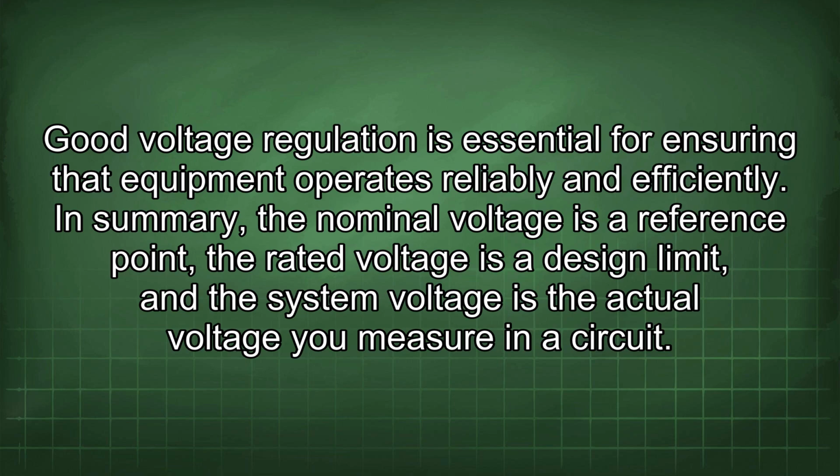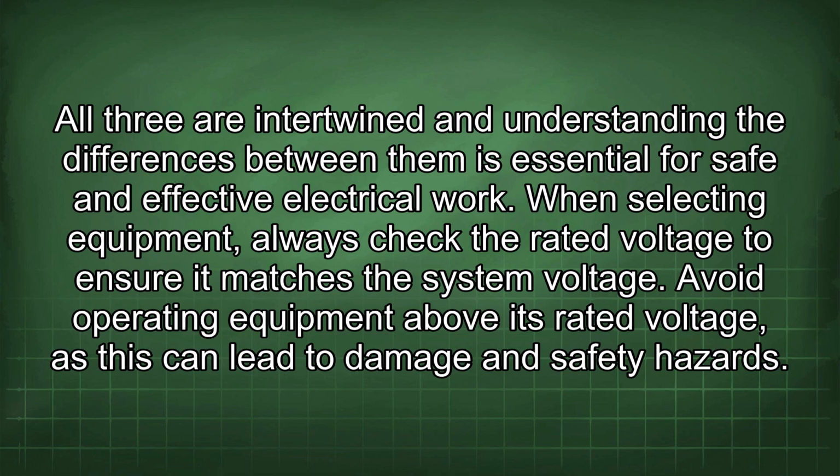In summary, the nominal voltage is a reference point, the rated voltage is a design limit, and the system voltage is the actual voltage you measure in a circuit. All three are intertwined, and understanding the differences between them is essential for safe and effective electrical work.